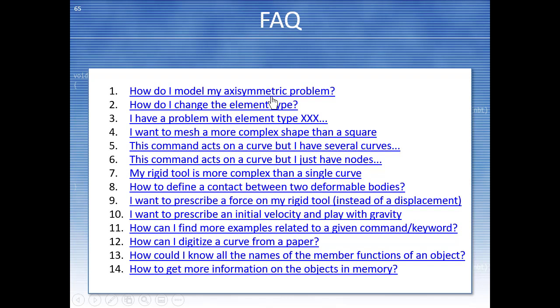So for example, if you have an elastic problem, classical elasticity, you can use almost any kind of element. But if you have rubber, some hyperelastic material, some elements will not work. There will be some additional unwanted stiffness. That's the same for plasticity. So plasticity introduces incompressibility because the plastic deformation is incompressible.